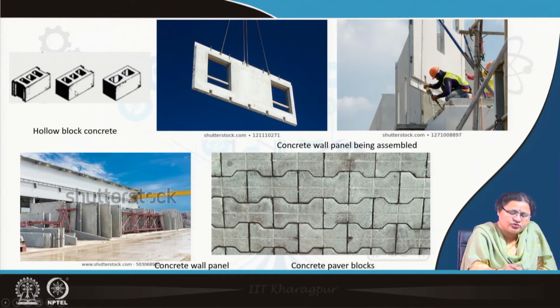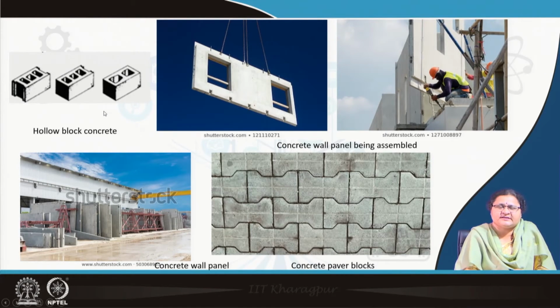So, here there is no notch. When you are starting or beginning your construction, you can start with this. When you are using these ends, you can interlock them. We will go into a little more detail in our next lecture maybe, but these are the first precast masonry units, called concrete masonry units.